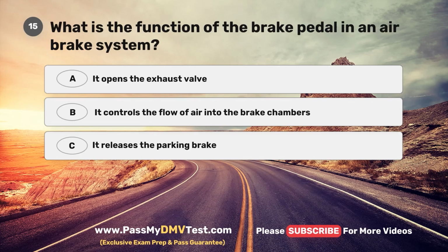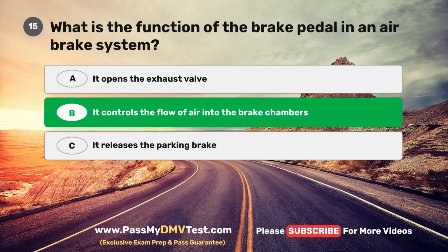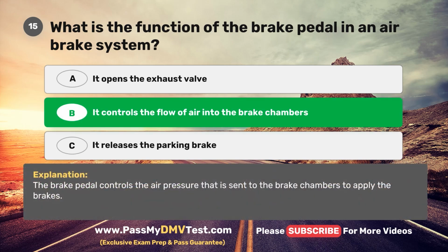Question 15. What is the function of the brake pedal in an air brake system? A. It opens the exhaust valve. B. It controls the flow of air into the brake chambers. C. It releases the parking brake. The correct answer is B. It controls the flow of air into the brake chambers. The brake pedal controls the air pressure that is sent to the brake chambers to apply the brakes.